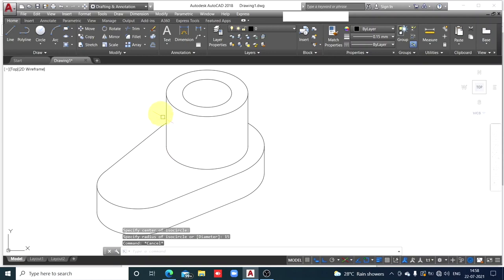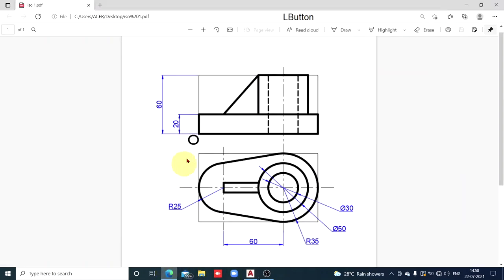These are edges of the object. Okay, must be thick, but thickness will give later. And now there is a triangular plate. Check here, this triangular plate. It has a width, that is nothing but thickness 10 millimeter. It's not given, so we'll assume it 10 millimeter. It appears half of that 20 millimeters.